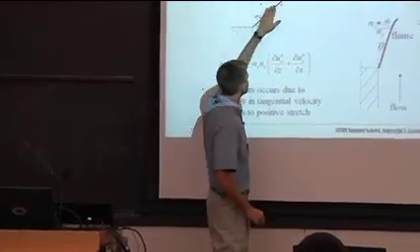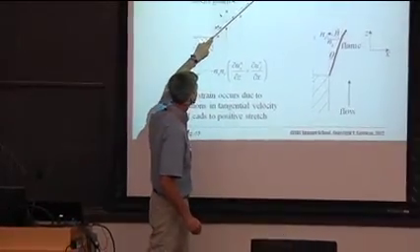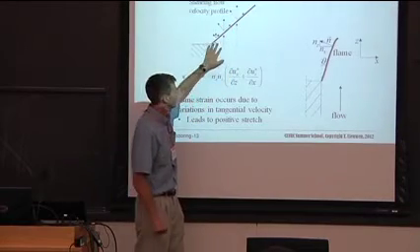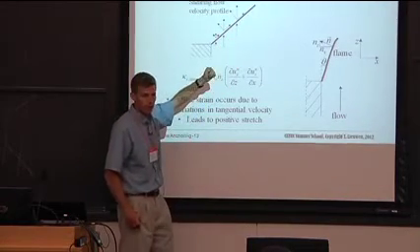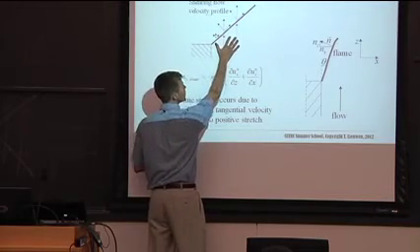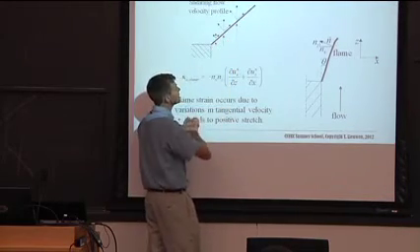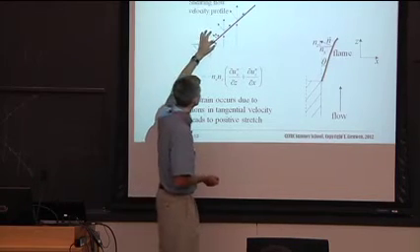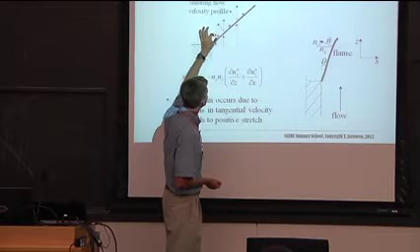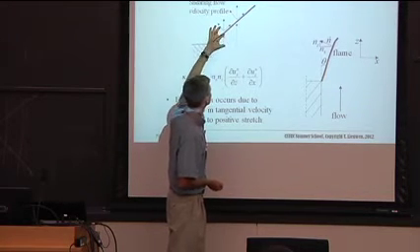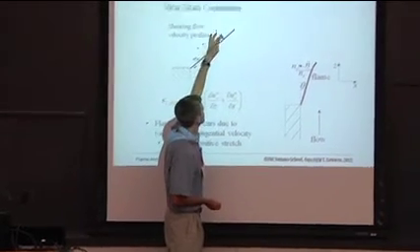So here I have a flame, it's stabilized in a shear layer, it's attached at this point, and I have this flow velocity profile. So clearly I've got shearing fluid mechanic deformation. But what is it doing to the flame? Let's take these flow vectors and decompose them into their components, normal and tangential to the flame. So I've taken this vector and decomposed it into a contribution normal and tangential to the flame. Same for this one, normal, tangential, normal, tangential.